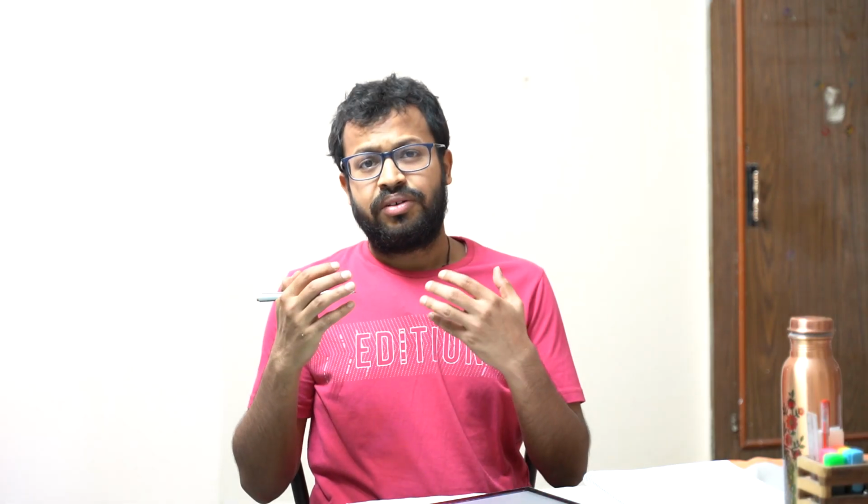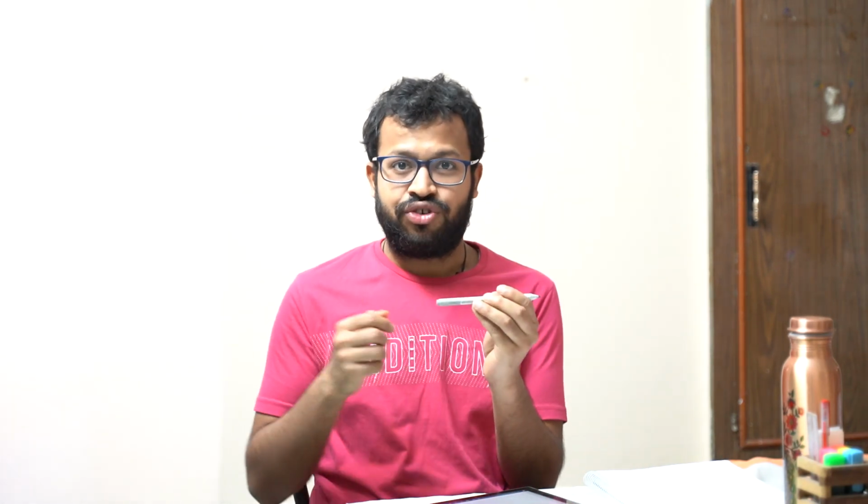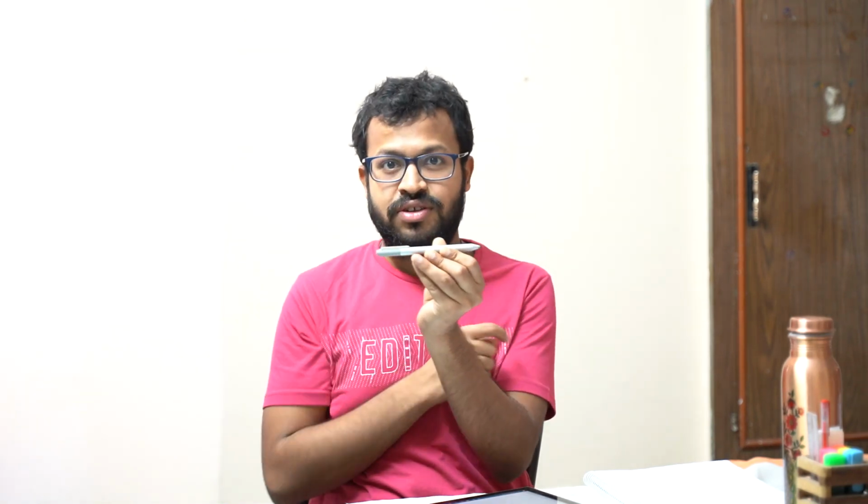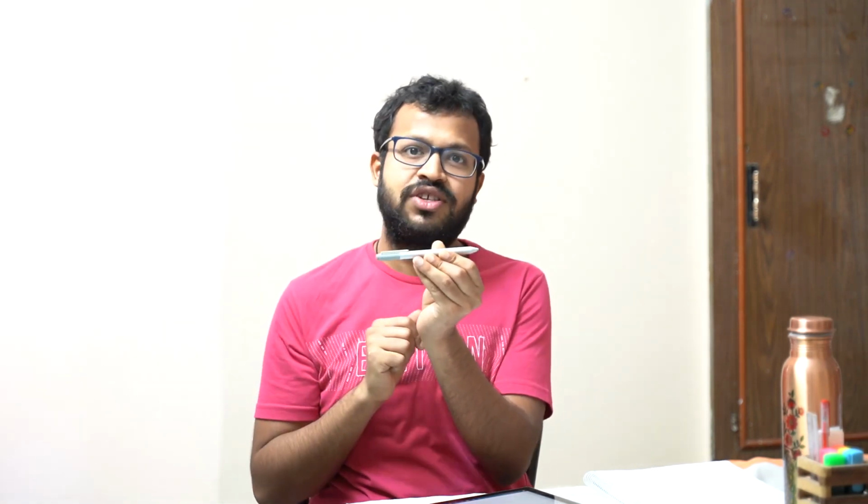The extreme cases are when this Peclet number is very large, a very strong convection. As soon as something happens here, it reaches all the way up to here. So we would have almost no variation until here, and then all of a sudden there would be very large variations. Remember that the boundary conditions are always fixed. This is always phi 0 and this is always phi L.